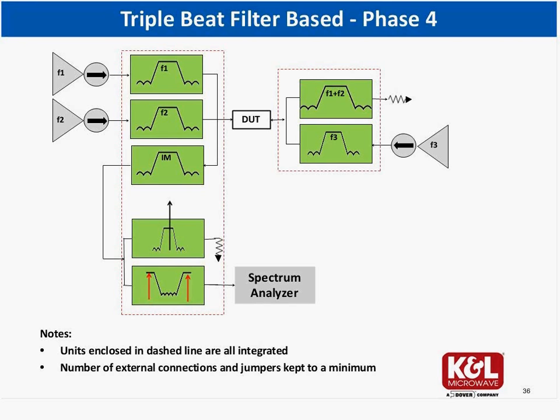They can cross over each other at 3 dB points, thus creating a complete S11 match port. What we found out is that customers can tolerate a sliver of frequency band, leaving a little bit of transition band in terms of the S11 match, and it did not really harm the setups.